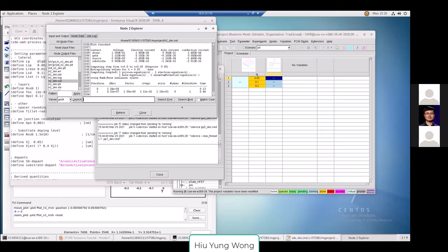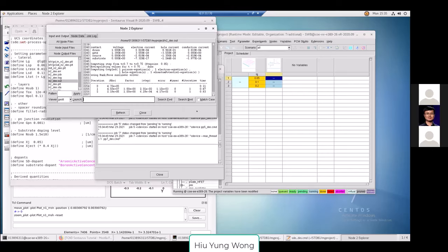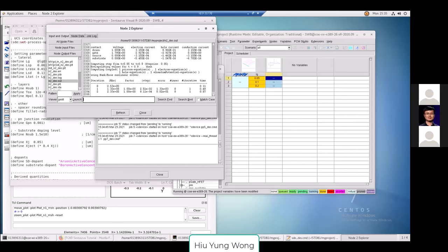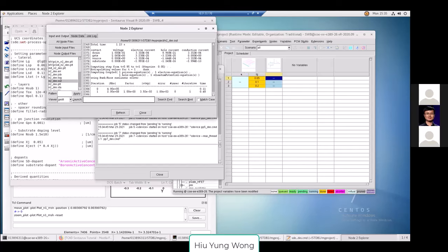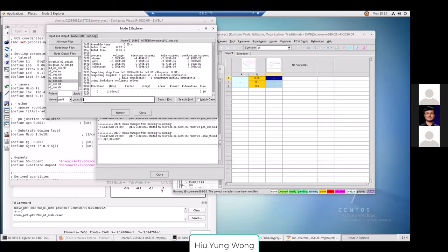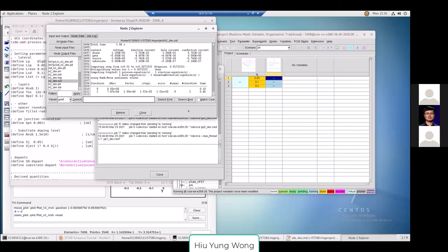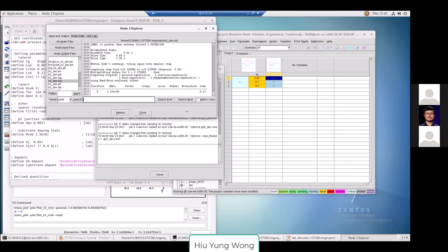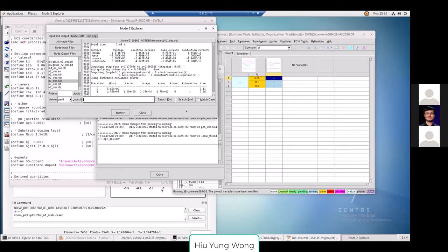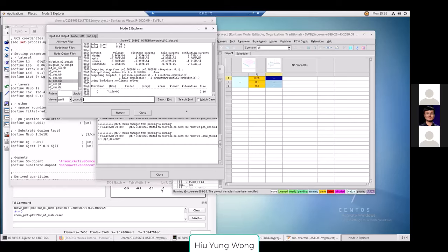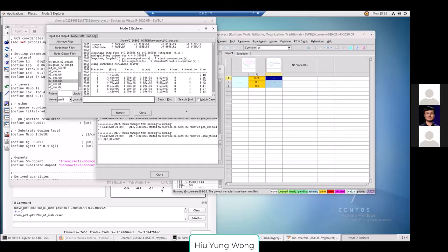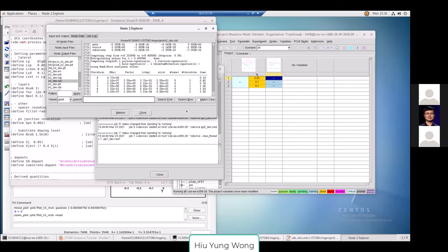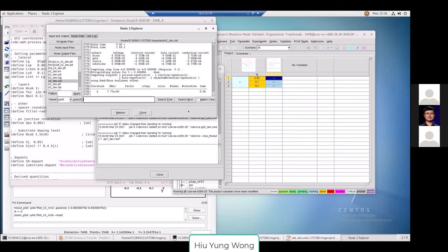You click on here, right click, and then say add parameter. Called LG. And are there any other things like list of values I should include? List of values, like what we are doing, 0.05, 0.1, 0.2.